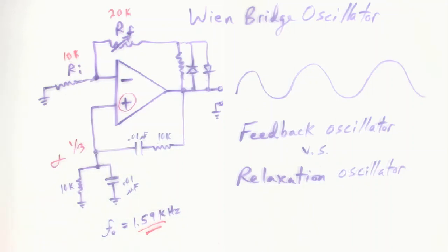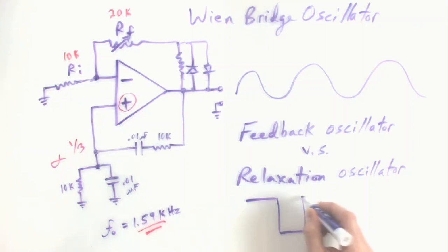And if you remember, with the 555, that's all built in. They had two comparators, both watching the cap, one setting a high threshold to turn on the discharge path, and the other one setting a low threshold to turn off the discharge path and let it charge back up. So the cap, as it charged up and discharged between two points, that's your relaxation oscillator. And the output of a relaxation oscillator might be high and then low, and then high and then low. So typically a square wave, some kind of rectangular wave coming from a relaxation oscillator. So there would be some context for you.